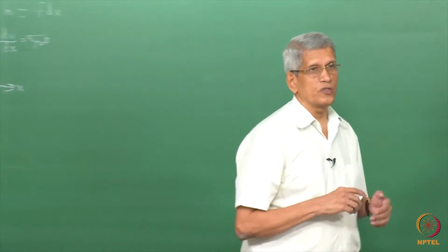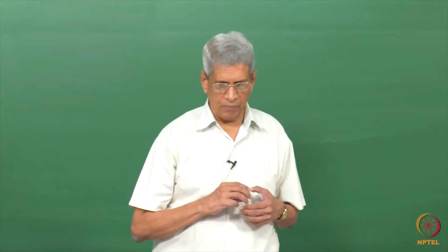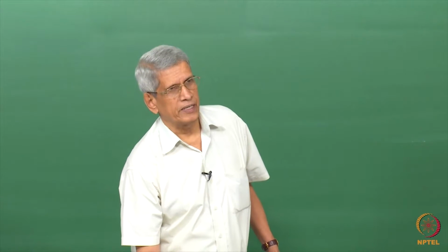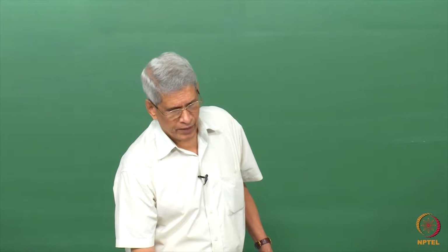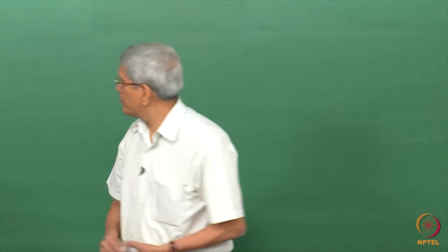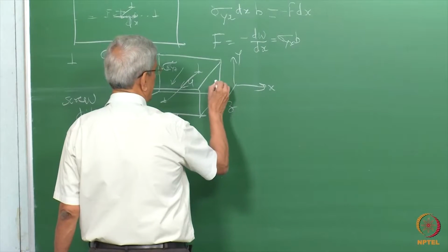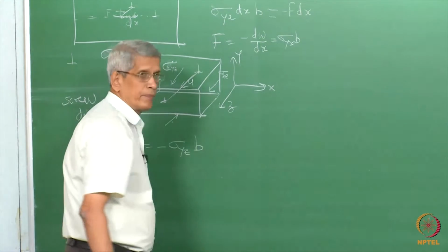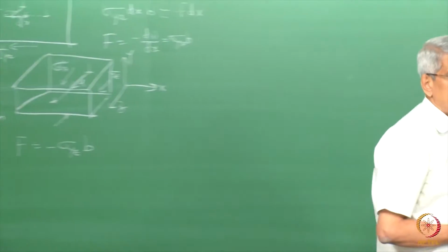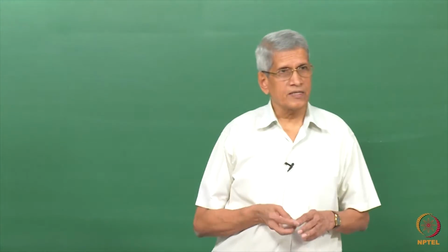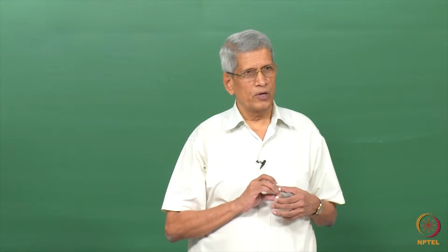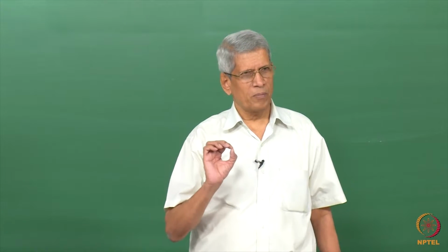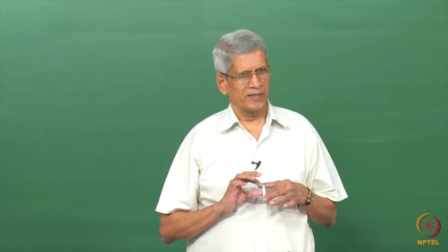But in which direction is this force going to act on the dislocation? That doesn't become very clear. Actually, this force will be acting in the x direction. Similarly, if a stress is applied on the x surface, sigma xz, the same thing will happen. But looking at the application of the external stress, we are not able to make out the direction in which the force is going to be applied. That is one of the problems of this way of looking at it.